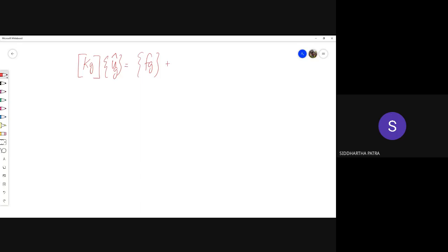Now, the second and the third equation are true, but the first equation may or may not be 0. So I need to add this residual over here. And I am not solving for u1, u2, and u3 from the set of three equations. There are indeed three equations now, three independent equations, but I am solving for u2 and u3 and r1 over here. Okay, so these are the unknowns.